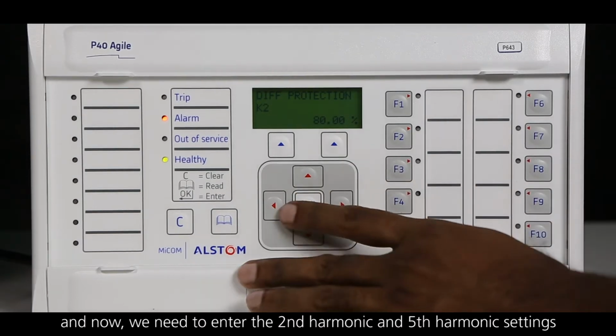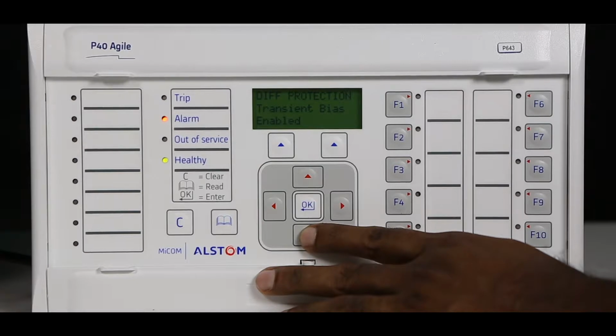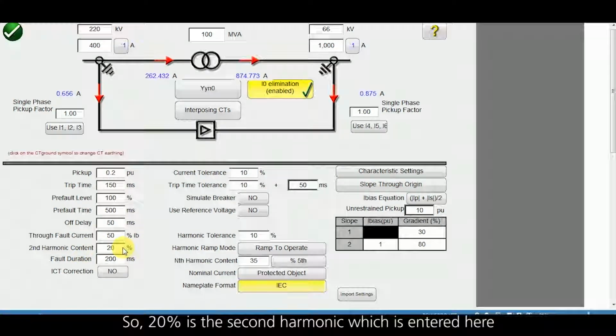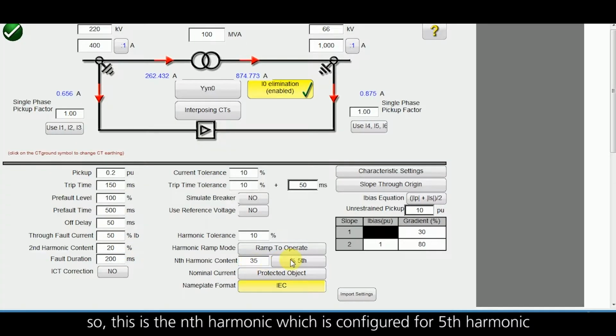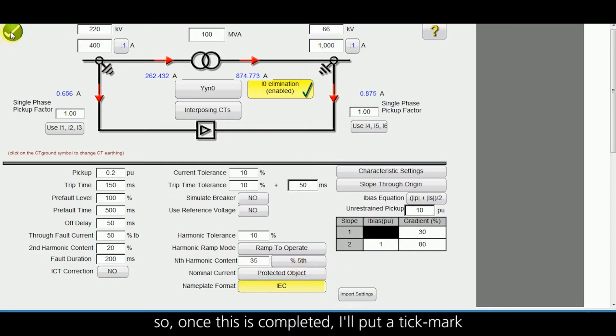Now we need to enter the second harmonic and fifth harmonic settings. 20% is the second harmonic, which is entered here, and the fifth harmonic is entered as 35%. So this is the nth harmonic setting, which is configured for fifth harmonic. Once this is completed, I will put a tick mark,